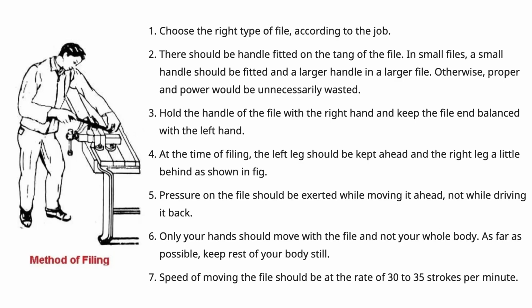This is about the proper positioning of filing, that is how to choose the right type of file according to the job. In this picture you see the way we file, the positioning of how you should do it. The file should run through the job from full length to the tang, to the handle of the file. In that you are supposed to stand and deliver the ability to file the job.